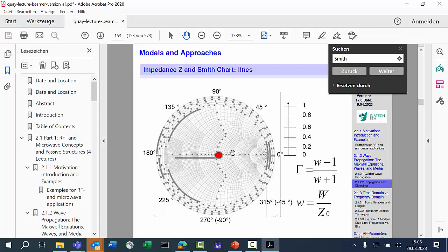So for example, this is 50 ohm and I'm connecting it to 100 ohms. Then I know there will be some reflection. Phase will still be zero. If I connect this to something which is capacitive, then I will also have some reflection and magnitude, but I'm getting an additional phase term. So it's not 0 or 180, but anything in between.